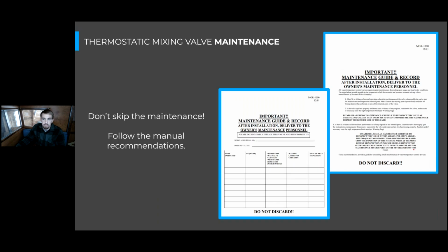Yeah, and Evan, someone was also commenting, basically saying another installation issue: plenty of shut off valves to isolate equipment for service. I think we had talked to that before, is making sure you're able to work on those specific sections and not have it affect the whole system. Yeah, that's a great point. You don't want to have to maintain the storage tank or the mixing valve and drain the entire domestic hot water system, right? You want to be able to isolate this one component so the rest of the system is untouched. So that's really important during the design and installation phase to ensure easy maintenance accessibility.